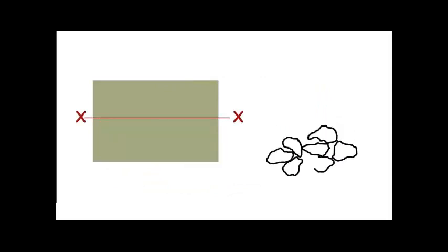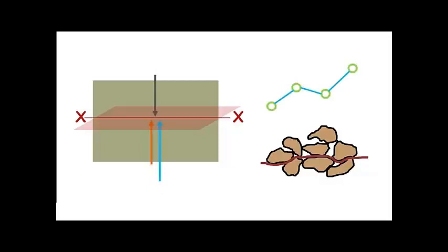Now take an imaginary plane XX at any level in the soil mass, which passes through all the points of contact between soil particles that lie in this plane. This plane looks wavy on the small scale, but for all practical purposes on the mass scale we can consider it perfectly plane. We will try to analyze the forces on this plane.